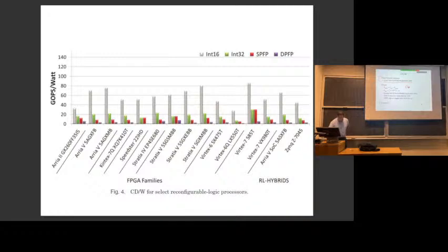So the capacitance goes down as you go to a new process node. Your wires get shorter. Your transistors, their area gets smaller. The wires also get closer together, but when you actually work out all of the basic physics of it, your capacitance goes down somewhere between linearly and quadratically as you scale. Okay, so you scale the process down by 70%, your capacitance is going to drop somewhere between 30% and 50%. Transistor capacitance drops more like 50, the wire more like 30.